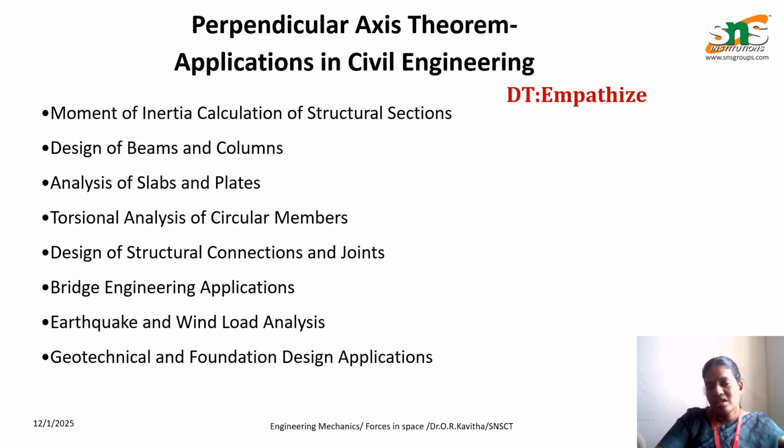So for the connections and joints, nowadays we are using bolts and welds. If the height of the structure is large, we are going for bolting. Whenever we are doing the bolting, the placing of bolts and the placing of holes are very important. So if you are not calculating the moment of inertia exactly, if you are wrongly placing the holes, that is the bolts in that place, there may be tearing of the bolts. So it will lead to the failure of the structure also. Therefore in that part also the moment of inertia is playing a vital role.